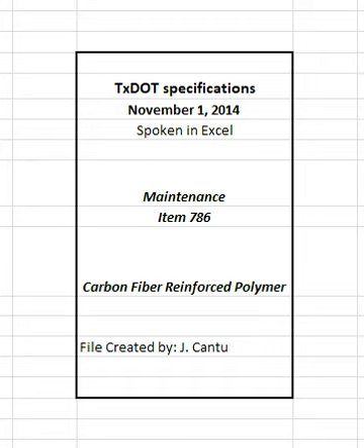3.6 Testing. Perform the following tests after the initial resin has cured at least 24 hours and in accordance with manufacturer's specifications: a visual inspection of the entire CFRP surface, an acoustic tap test of any area suspected to contain air pockets, and at least 2 direct pull-off tests for each member strengthened in accordance with ASTM D4541 to verify the tensile bond between the concrete and the CFRP system. The engineer will select areas to perform the direct pull-off test.